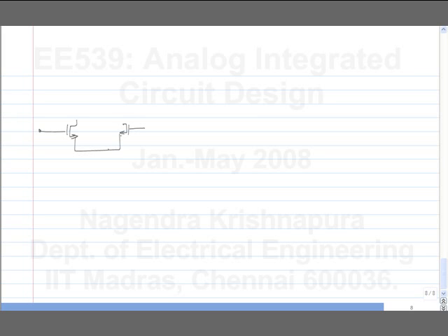I'll draw only one half, and I want finally a picture like this. I want this bias current plus the signal current that is flowing in. And his suggestion is to use this. So I have a certain bias plus increment here, okay, and that can be mirrored into another transistor, okay.